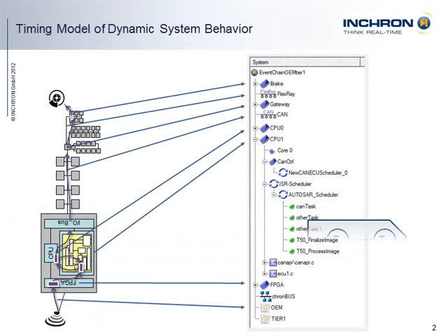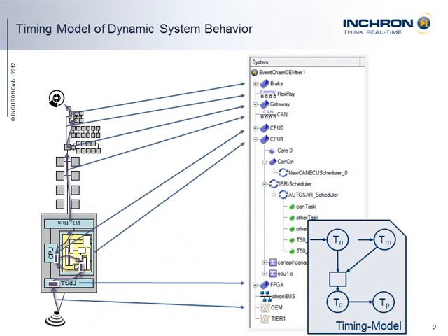Starting point is a model-based approach for three good reasons. The OEM can model and analyze the end-to-end event chain before the system has been built and integrated. And the ECU developer can derive the robust and reliable architecture in the system and the software design phase. Secondly, through abstraction, we get rid of the complexity of all the details. We really focus on the timing. And third, design alternatives can be evaluated and compared very fast in short iterations, sometimes within minutes. Unthinkable if you would have to implement, integrate, and test them using real hardware.